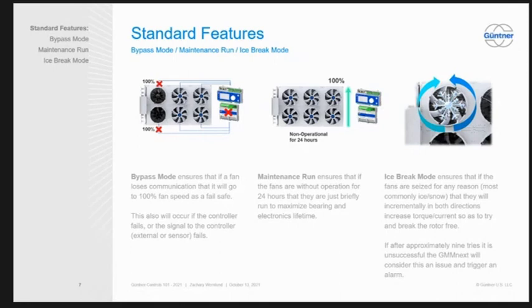Yeah, it's a good question. What a lot of customers are doing is, for instance, let's say it's a 6-fan unit with 2 coils, one on each side, and they want to split the unit. On our controller, you can do it. What I would suggest in that case is to send two 0 to 10 volt signals, one for each side: 0 to 10 for the left side coil, 0 to 10 for the right side coil. When you don't need any cooling on the right side, you just give it a 0% fan speed, and it doesn't run the right side, and the left side runs however you need it to.